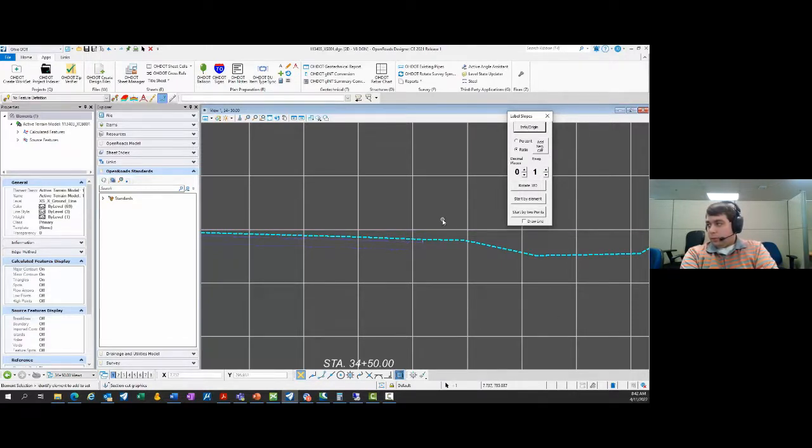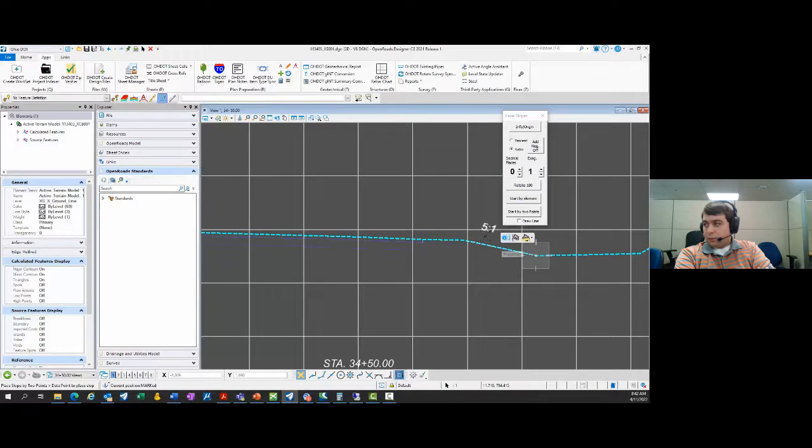So I should be demoing this, if I planned out what I wanted to say with my length of video, right? So I'm going to click those 2 points and then I'm going to data point, and you'll notice that it is integrated with AccuSnap, so you can snap to what you need to. Data point, and you'll see there's a line being drawn. That line is temporary unless you check on the draw line checkbox. If I check that on, then it will persist into the model and be there more like a reference for you. So I click my 2 points and then it calculates the slope, and now I can place that slope or that annotation wherever I want.